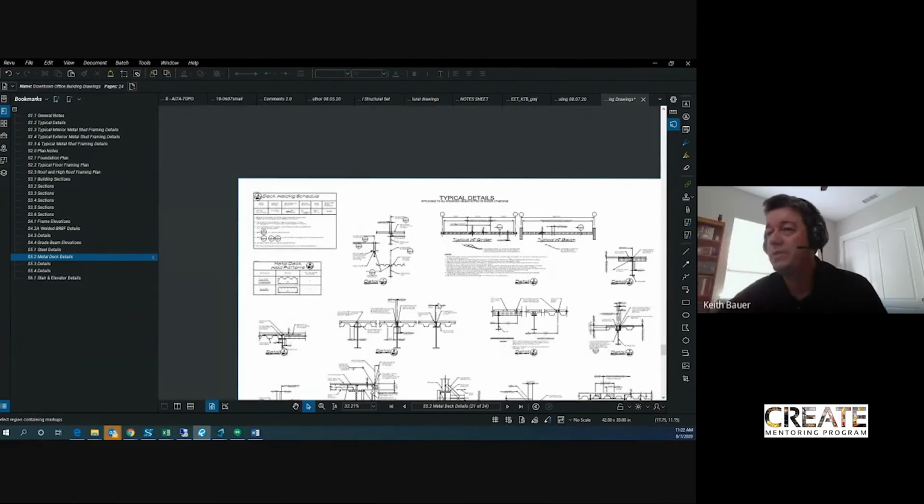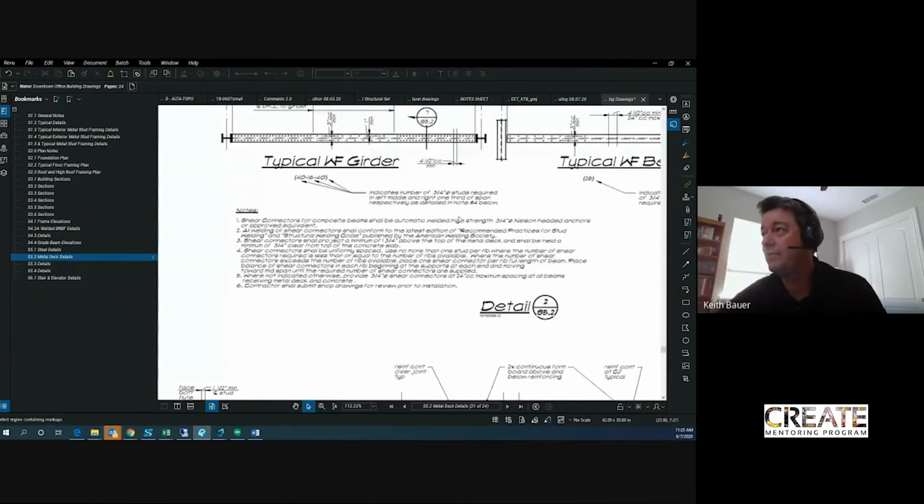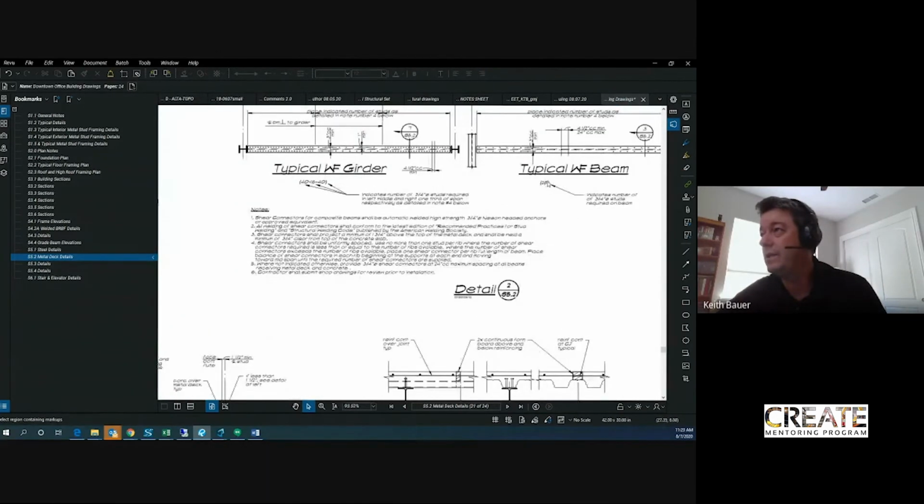We talked earlier about studs on the beams, right? And how they're studs that stick up into the concrete. So this detail right here explains what those callouts mean. So you got 28 in parentheses next to the beam. That means you have 28 studs, and they're 3/4 inch in diameter. If you see something like this, and there are callouts like this on plan, I can show you one in a second, where it's 40, 16, 14, or 40, 16, 40. And then it shows kind of graphically, see how there's 40 all clustered in this area, then 16, then 40.